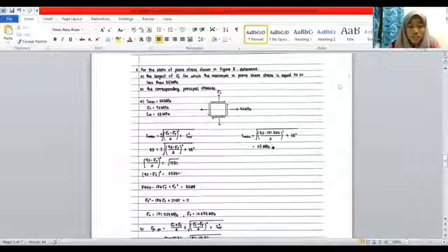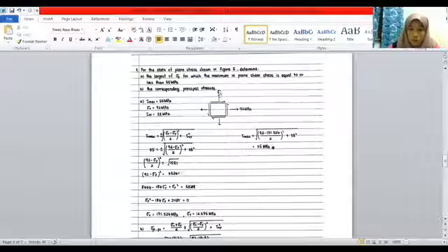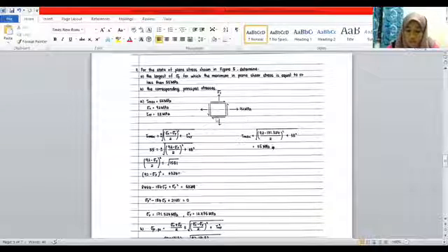For question number 7, it requires us to find the largest value of sigma y, where the maximum shear stress is 55 MPa. From the figure, we know that sigma y is positive as the arrow is pointed outward, and sigma x is positive 92 as the arrow also pointed outward, and the shear stress is 38 MPa positive as the arrow is pointed towards the positive axis.